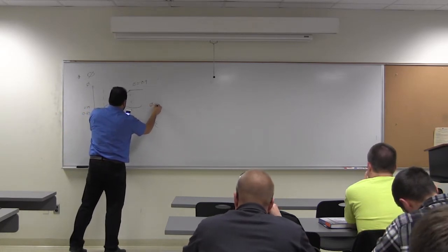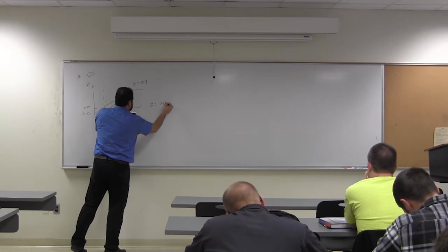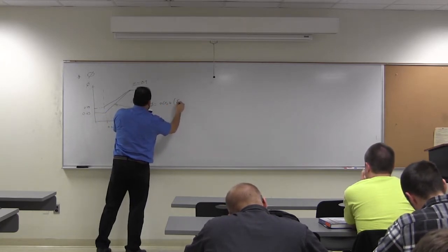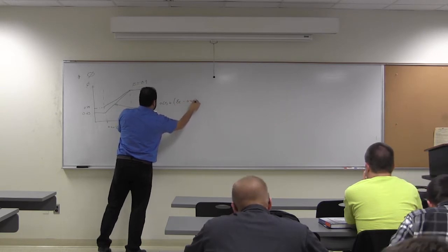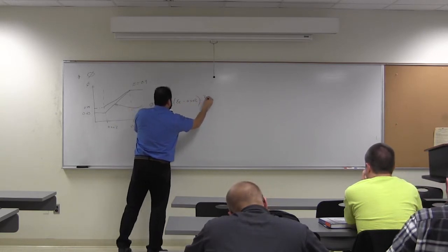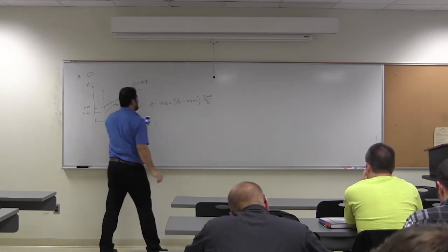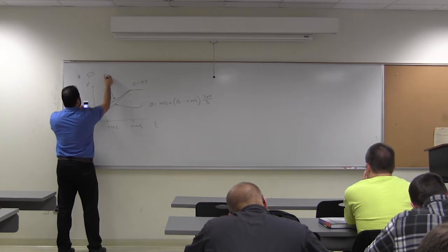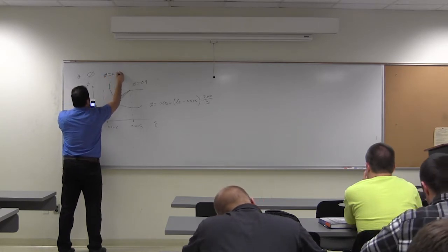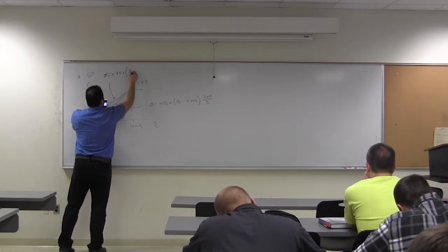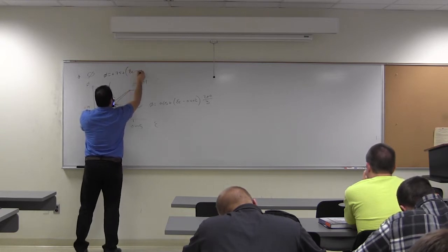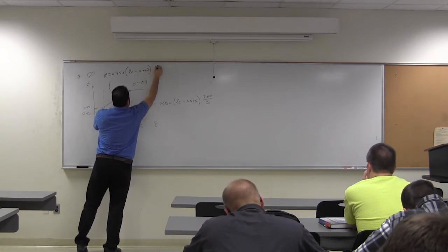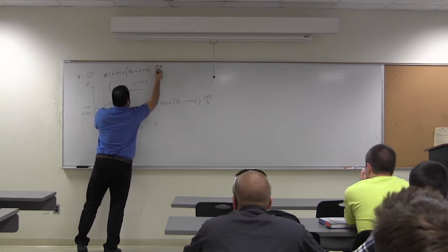Phi equals 0.65 plus (epsilon t minus 0.002) times 200 over 3 for the tied case. And for the spiral, Phi equals 0.75 plus (epsilon t minus 0.002) times 150 over 3, or 50.